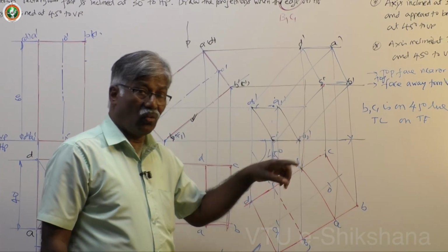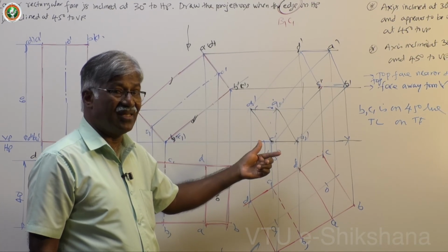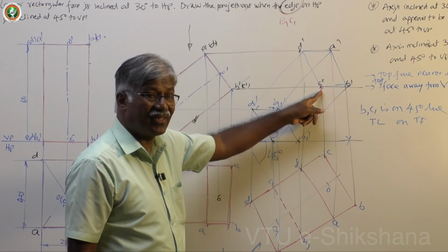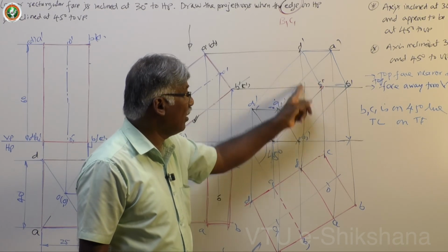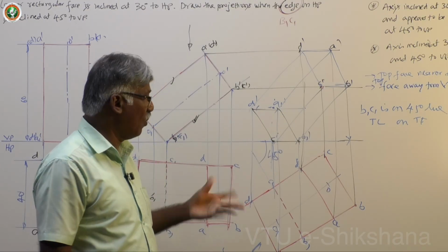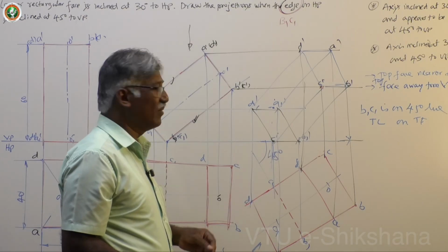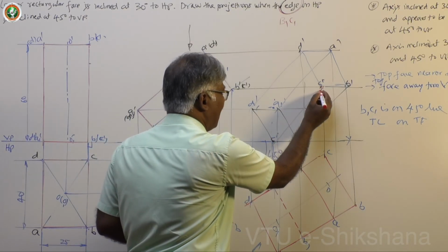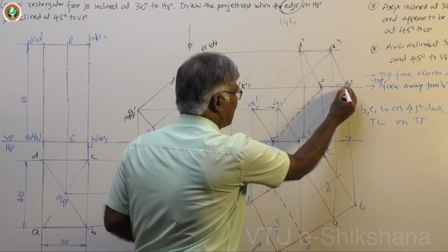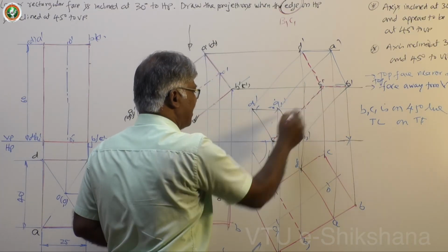Now whether to go ahead with the farthest point method or not, you can check easily. See, line joining this particular point, farthest point from you, all are within the boundary. Definitely you can complete this problem within no time. How? See, this point is not visible, farthest point from you is not visible. Then the lines connecting to that point are these: D1 C1, C1 B1, CC1.